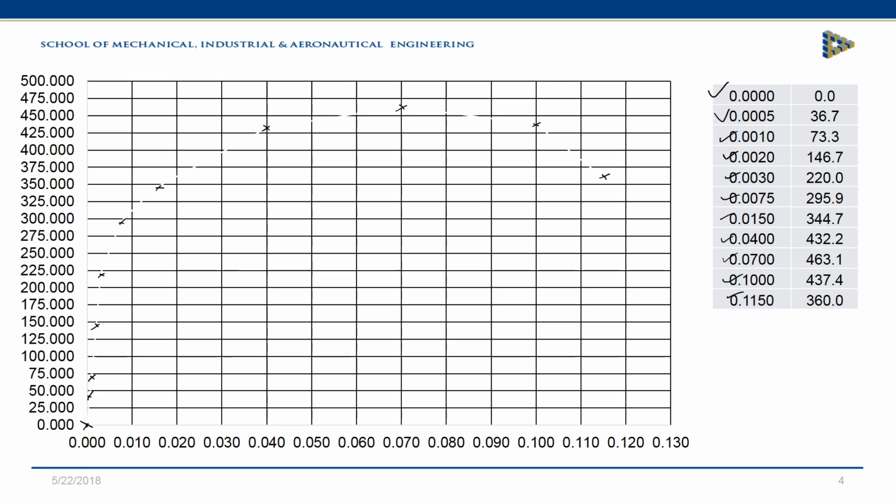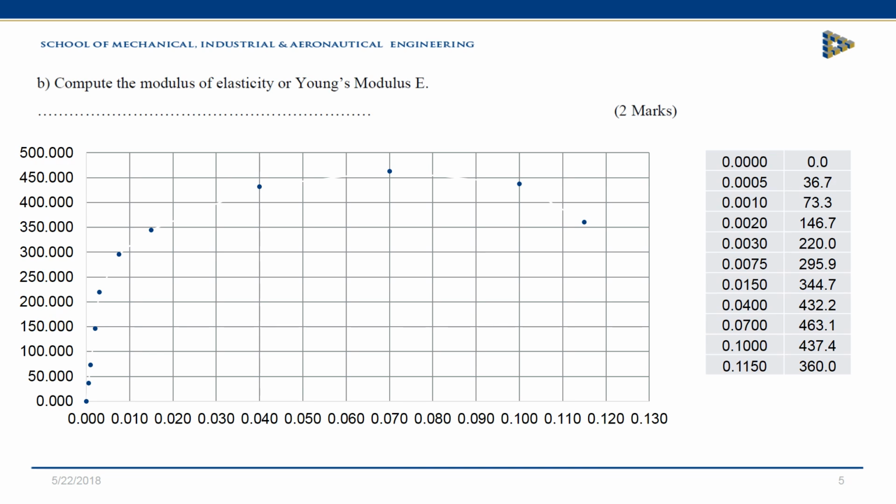Okay, so now I can draw this curve. I have to label my diagram. So this is strain, and this is stress in MPa. Remember, the units are important. Now I'm going to draw a curve. I do apologize, my drawings are not the best at the best of times. But it would look something like that. And already I can see that my UTS is there. So this is my UTS point, and this is obviously my breaking strength. You would obviously draw that a lot neater than I have, but that is basically what we're doing.